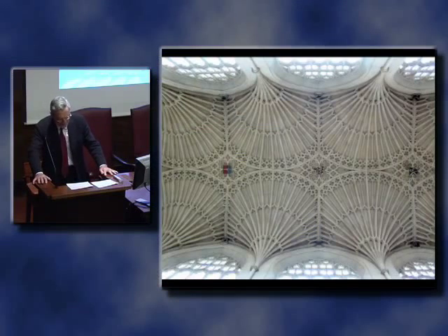As Brunelleschi stated in Florence, and of course he was not believed until 18 years later, but he did manage to build the dome of Santa Maria del Fiore without too much centering, as opposed to the fan vault, where the equations imply that not only are the force systems going to be different, with a tendency, almost requirement, that you are going to have tension until you completed the structure, and the fact that construction is going to be very difficult indeed compared with Brunelleschi's dome.